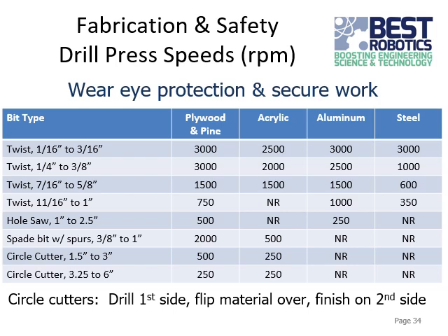And then for drill presses, I've added this table here. This is just for reference, but you can find it online. A lot of drill presses, at least that I've seen, have a little table like this for reference, either taped inside the cover or something like that, so that you always know how to use it. But in general, with smaller drill bits and smaller things, you can go faster. With bigger ones and hole saws, you need to go a lot slower.